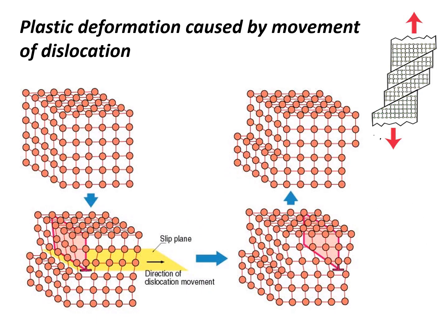Now you see with the help of this diagram again, you better understand. So this is a plastic deformation caused by the movement of the dislocation. You see, this is up to the point B, up to the elastic limit. Now you cross the elastic limit. You see, this is the slip plane in the yellow region. So this is the slip plane. And you see, this is the dislocation. Now you see the metal bond breaks here and you are getting the dislocation here, because you see now in its continuation, there is no bond. So this is the dislocation we are getting.